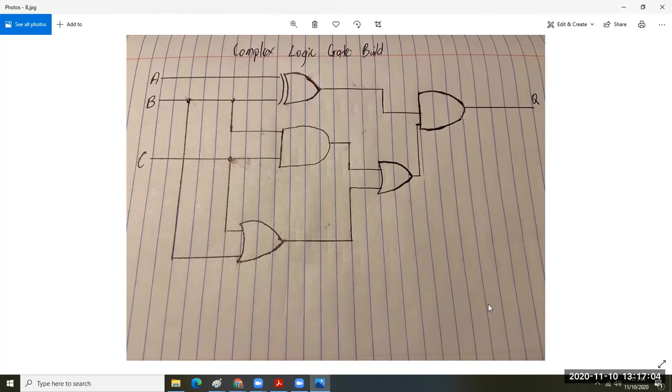Okay, so again, this would score additional credit. This designer included more than just 3 logic gates and included forks, splits, right? I believe that's the XOR. And then we have 2 ANDs and 2 ORs. Very nice. And that's easy to follow. So we have A, B, and C inputs and at the top of the XOR, and then B forks down here into the bottom of OR and into the bottom of the XOR and then into the top of the AND. And then C does something like this too.